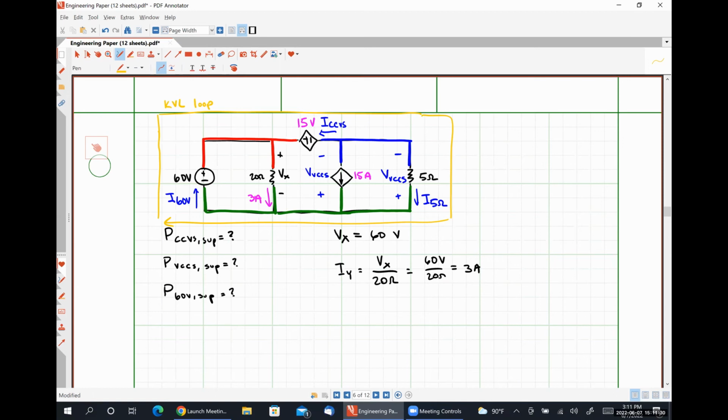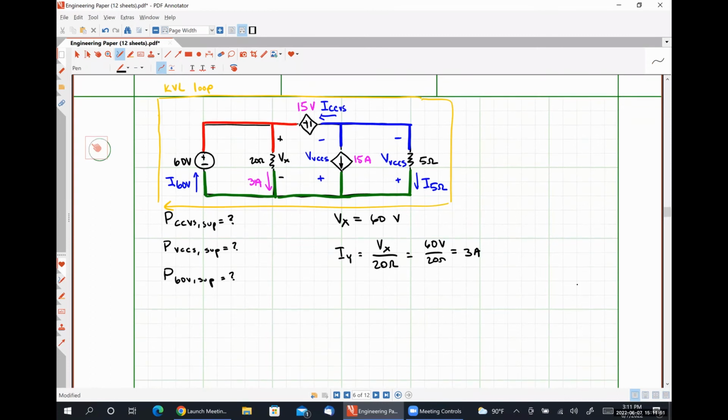Across the middle bit on top, we have a known voltage of 15 volts. Across the right-hand side, we have that unknown quantity. And across the bottom, we have a voltage drop of 0 because those are all just wires or short circuits. And we know that the voltage drop across the short circuit is 0. So somebody help me out and tell me how to write a KVL expression following that path I've outlined in gold.